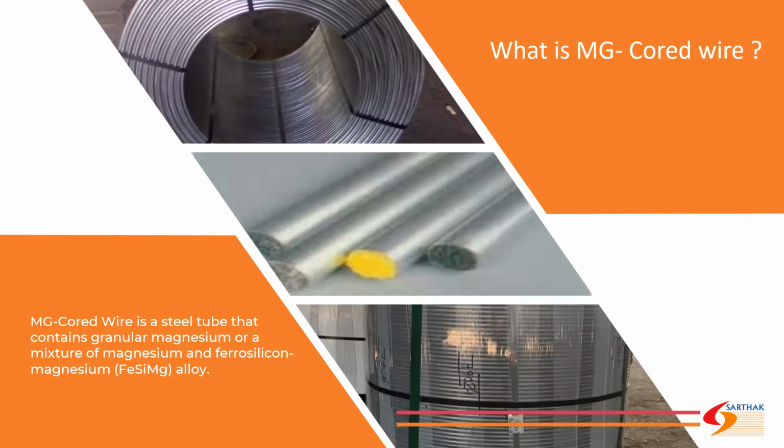The magnesium granules or magnesium alloy powder are encased in a steel or CRCA sheet, which forms a core wire, and that core wire we are feeding into the metal at a certain speed with the help of wire feeding machines.